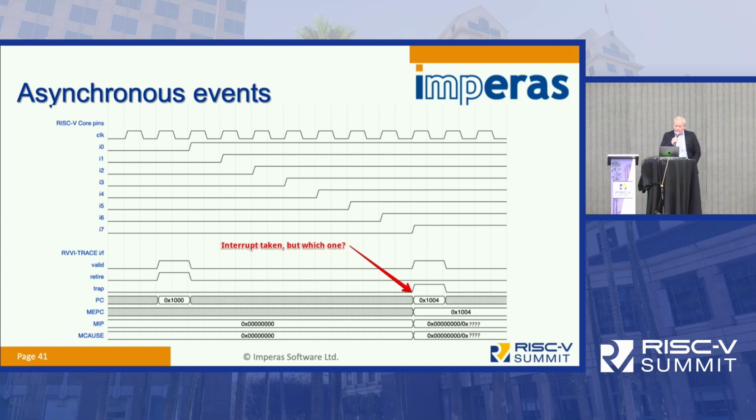And in fact, this is quite a simple example that I'm going to show here, but we have some really complex examples in Core 5 DV where using the instruction stream generator, we would have situations such as a return from an exception would then have been preceded by another interrupt being asserted, and it was returning to an address of an instruction which had a debug breakpoint address placed upon it, and you also had an e-break instruction at that address.